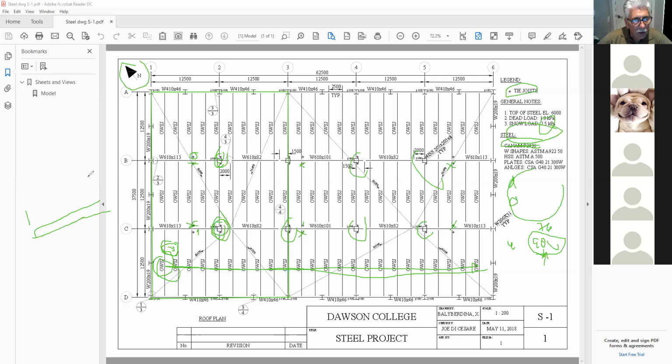Oh, with that long equation. Here you have AGV, right? You're going to have 2 holes in your gusset plate. Okay, so we're checking the bearing? Yes, you have to check the bearing in the gusset plate, but you shouldn't have to worry about it because you've already checked it on the HSS. The bearing would be the same if you're using the same thickness. Let me just clear this so that we're on the same page.